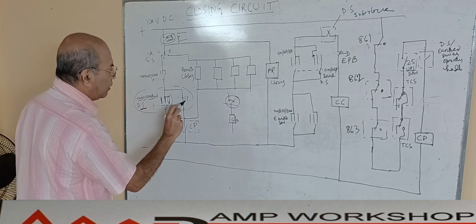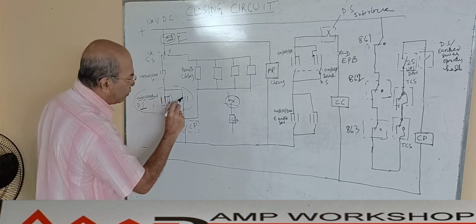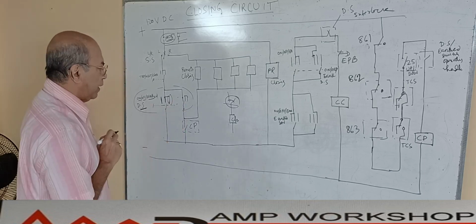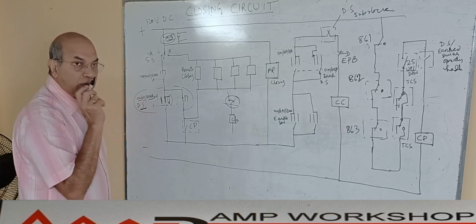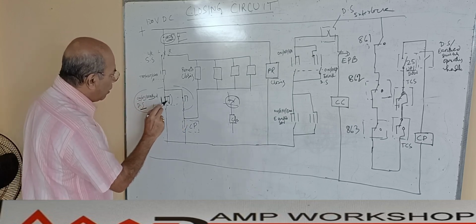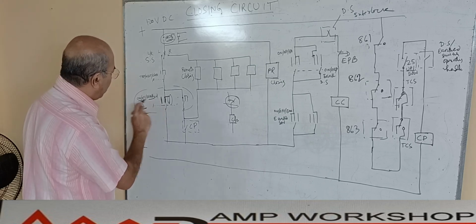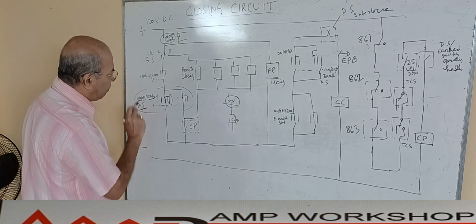Similarly, this is interlocked with the second set of contact. Here also this is on position, this is off, and this is earth position, and these two are common position, you can say. Now you see, when we are going to do the test, we will be using this position. Means isolator is off position. You see this center is off position.